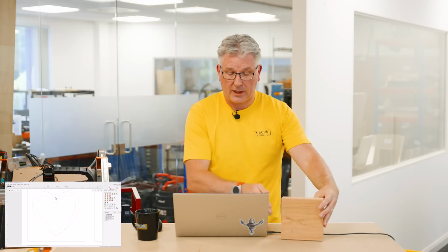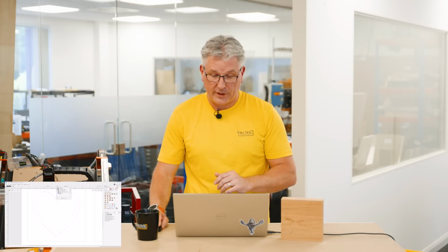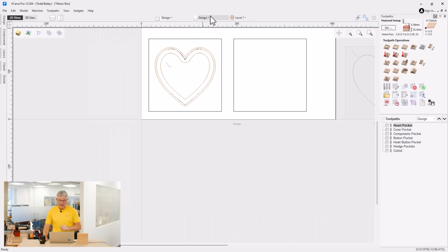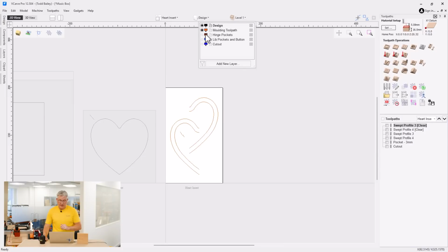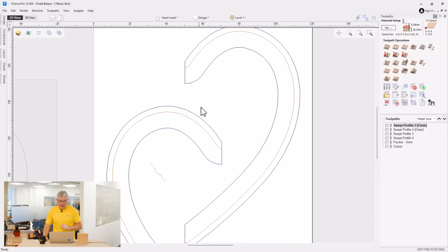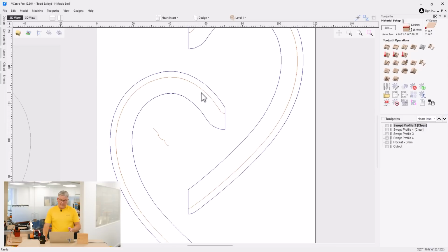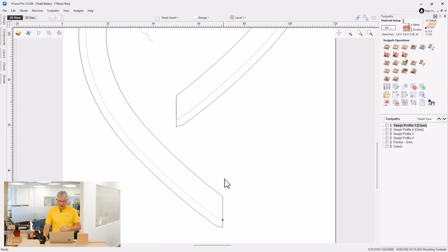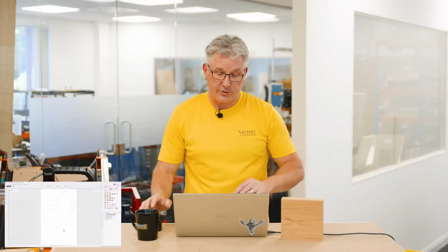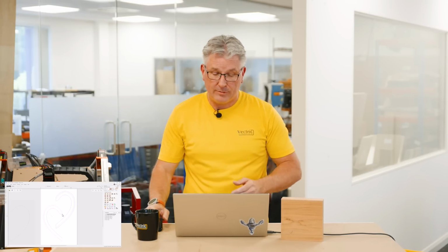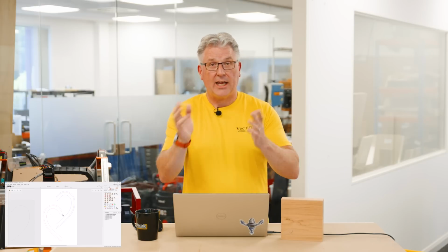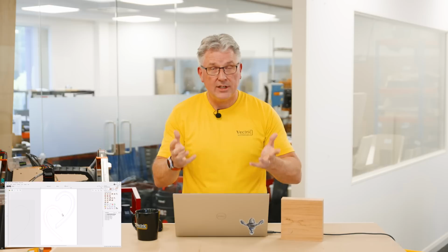Now let's zip over to the actual sheet that I use to cut the two parts of. So if I go ahead and have a look at my sheet, sorry, over here to my heart insert sheet. So I've turned it on and it's over here. And we're going to turn on all of our layers so I can see everything that I need. Here we have it. We've got that half drive rail that you saw me make a minute ago, with that little radius in the corner there, the top and the bottom. I've cut it in half to fit my material so it looks really good. My cutout pass literally is those two offset vectors that you saw. I've just gone ahead and trimmed them down and connected them up with a straight line so I can use this as my cutout pass. And if I'm lucky, everything should work out okay.